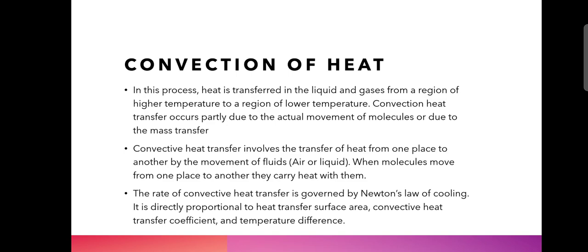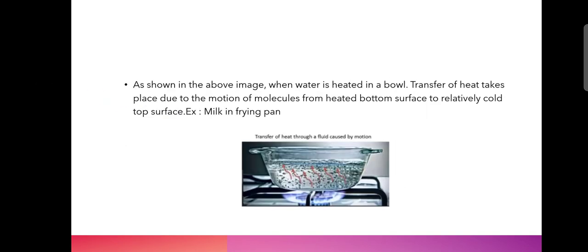When molecules move from one place to another, they carry heat with them. The rate of convection heat transfer is governed by Newton's law of cooling. It is directly proportional to the heat transfer surface area, the convective heat transfer coefficient and the temperature difference.